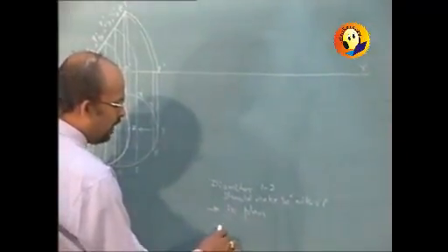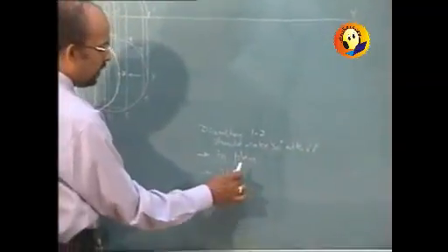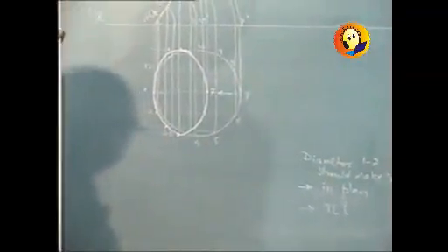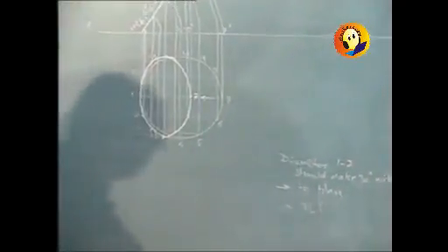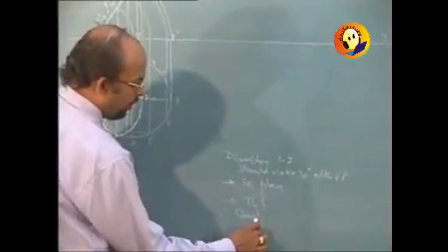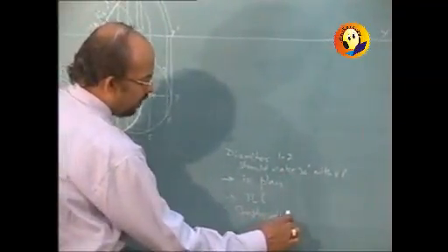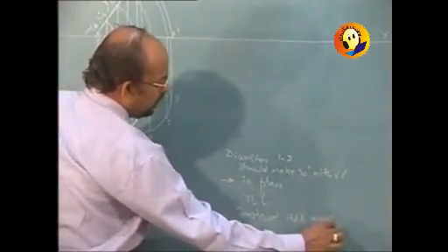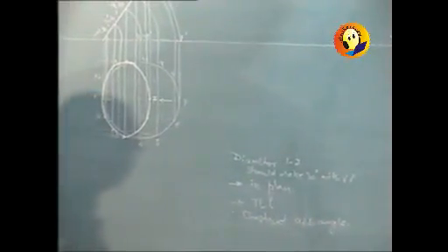But we will have to check whether we have the true length, and we find that 1/7, as we are getting it over here, is not the true length, and therefore we are required to construct the apparent angle, because true length will be associated with true angle and apparent length will be associated with apparent angle.